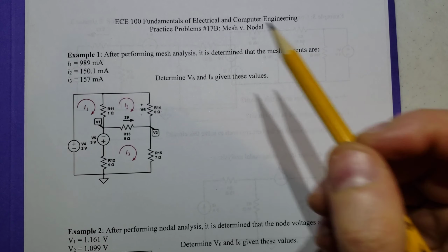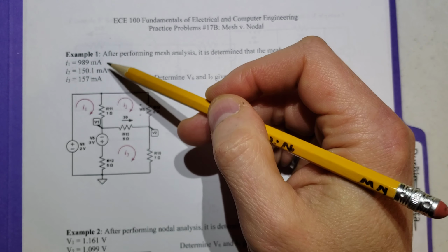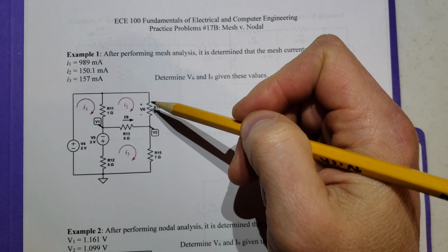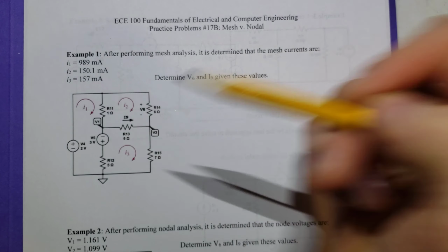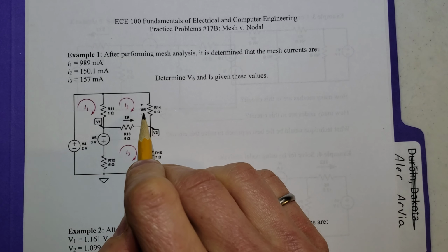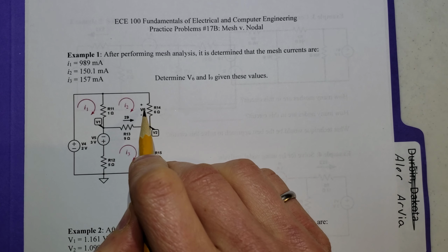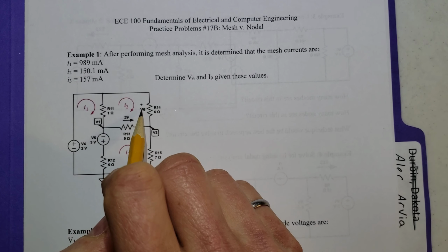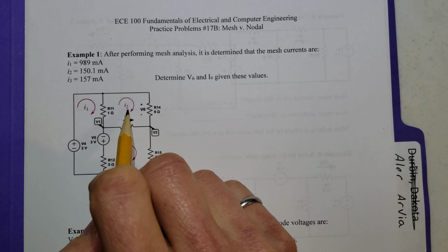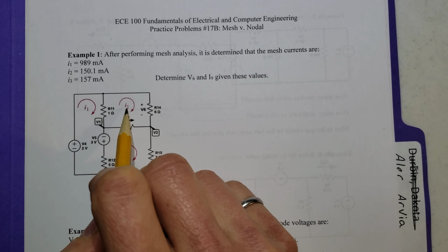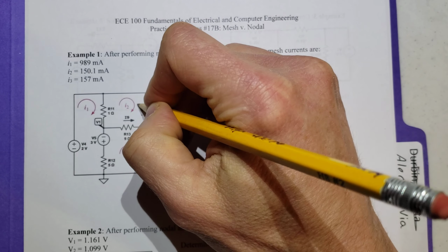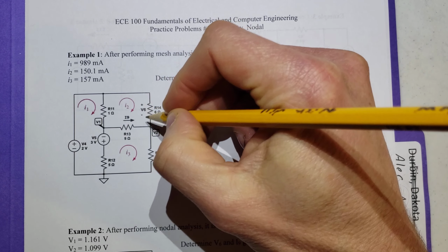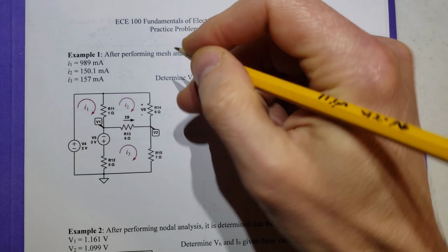But I wanted to emphasize, once we get those characteristic currents or voltages, then solving for other currents and voltages across components is easy. So for example here, let's talk about V6. Now assume we've solved with mesh analysis, and we want to find V6, and we have the value for I2. So the current going through this resistor is I2, and I2 is going around clockwise, and so it's entering the positive node.